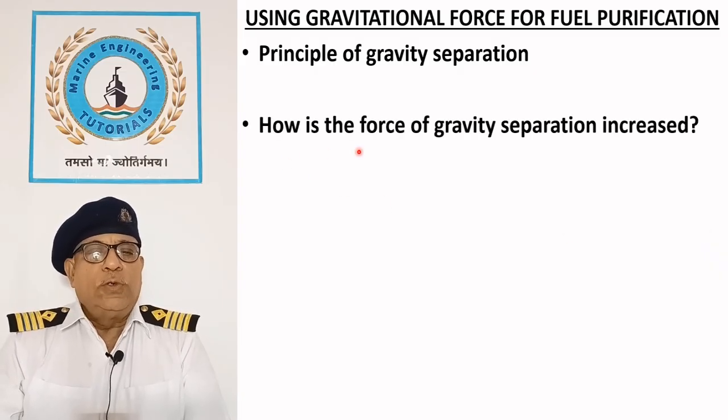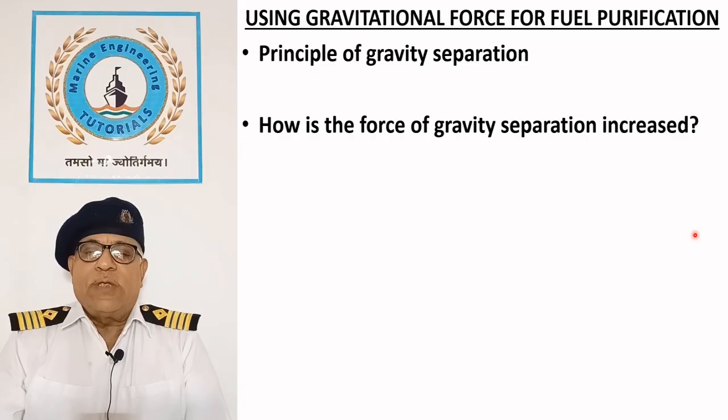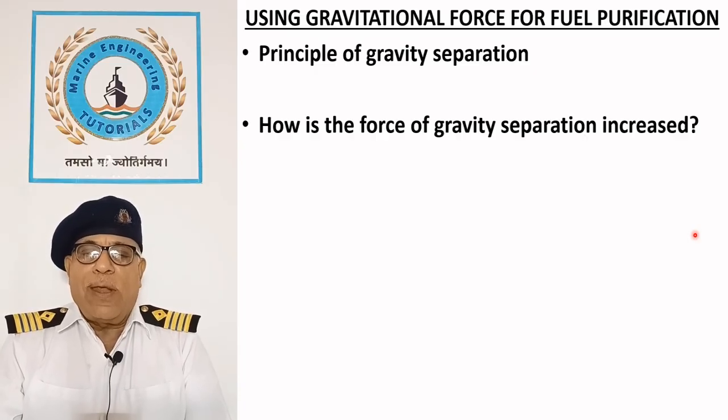How is the force of gravity separation increased? Force of gravity separation is further increased by heating the fuel oil to a temperature of about 75 degrees Celsius, due to which the density difference between oil and water increases and it helps in their separation.